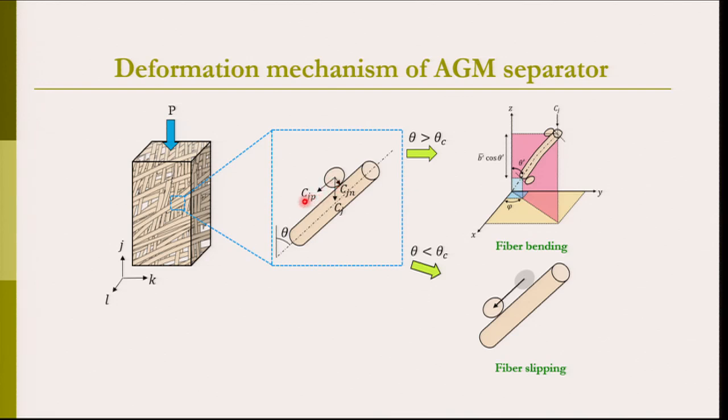Since the stretching phenomenon is least expected in glass fibers, because the bending stiffness of the fiber is lower than the tensile stiffness, the chances of bending during compression load would be much higher. So, let us assume the bending deformation of the fiber is taking place within the structure. Now, there are two possibilities again.